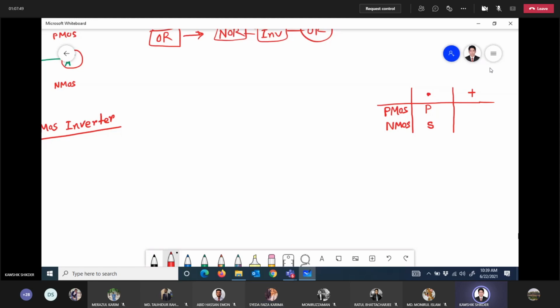Noted, everybody? Yes, sir. And if the sign is plus, the PMOS should be series and NMOS parallel. Okay, just the opposite. So to design CMOS NAND and CMOS NOR, you have to follow this table along with the formation. So suppose CMOS NAND, what is the equation?